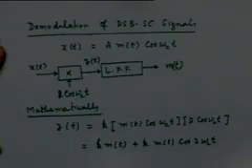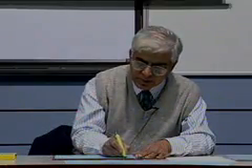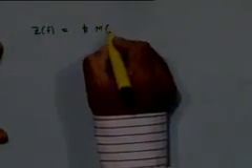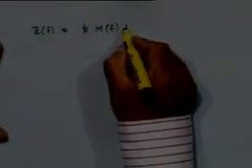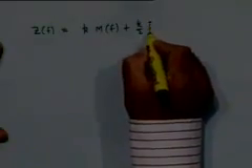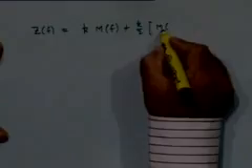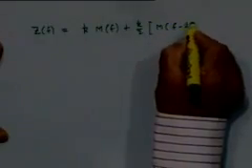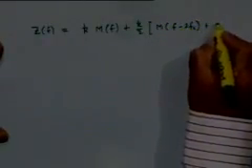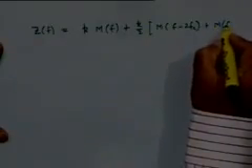And in the frequency domain, if I take the Fourier transform of this signal, the first part will have a Fourier transform which is k times the desired spectrum M of f, plus you have components at the translated versions of M of f around 2fc and around minus 2fc.